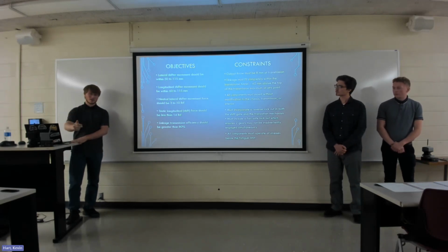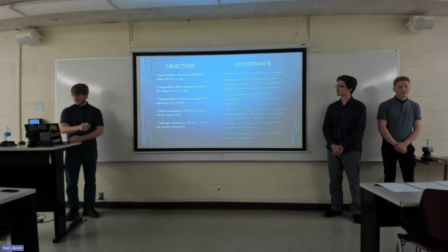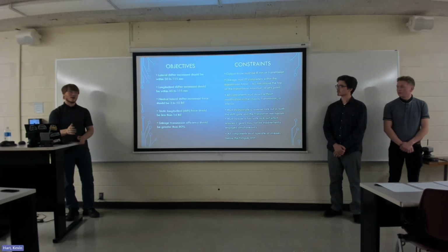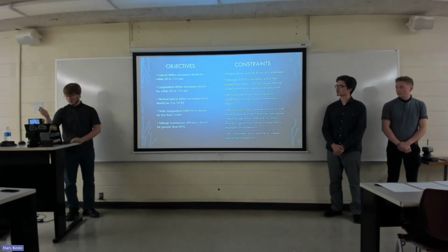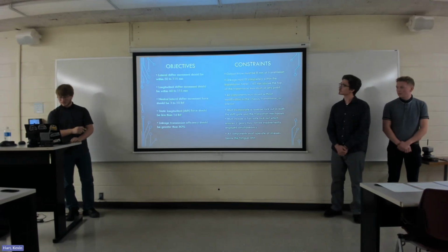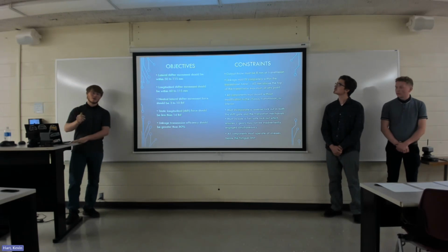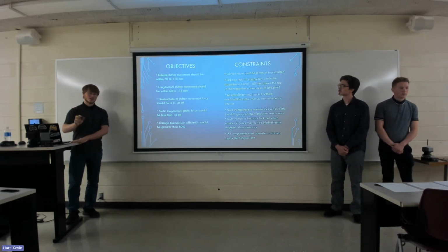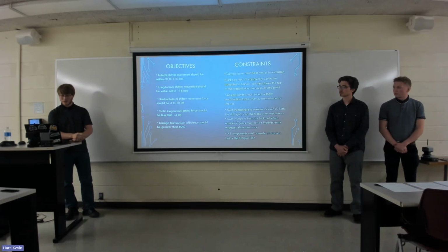Again, we're now moving to the neutral lateral force. This is while the shifter is in neutral, if you move the shift lever over to a different gate without engaging the gate. That was between 3 to 10 pounds, and that depends on how many gates you're moving over. We'll talk more on that in a couple slides. So this is the big one, the longitudinal shift force. This is the amount of force that it takes to push the hand shifter into a gear while the car is stationary. Our goal is to be under 14 pounds.